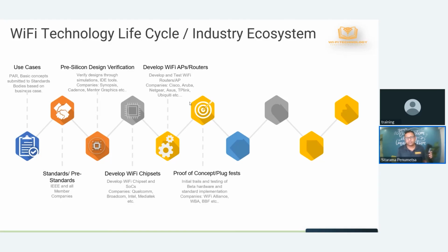And then once you build the early version, even before you get to this stage, at the board level itself, you go do proof of concept. Then you go do plug fest. As the new technology comes out, you need to make sure that this Wi-Fi router can connect to a Wi-Fi device, right? So you'll have to do some initial tests, and there are organizations like Wi-Fi Alliance and so on that do this plug fest, right? And then you go through certifications.